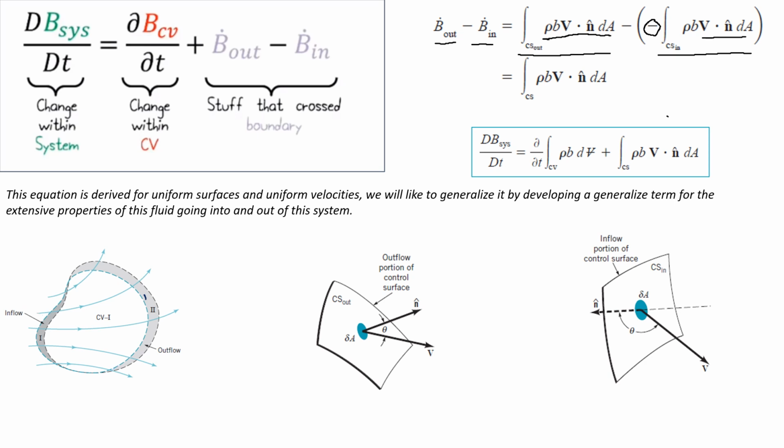So what happens when this system interacts with this control volume, or moves through this control volume? We needed a relation, which was provided to us by the Reynolds transport theorem. Reynolds transport theorem begins its arguments by taking the extensive properties for the system and applying those properties when that system is moving through the control volume.